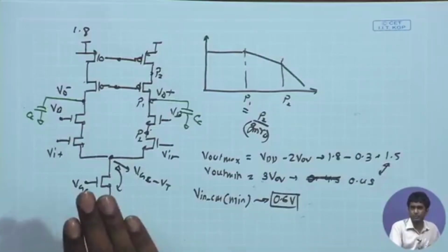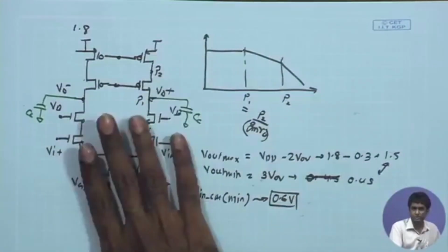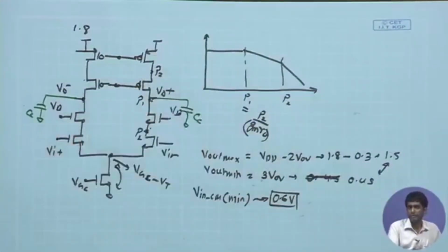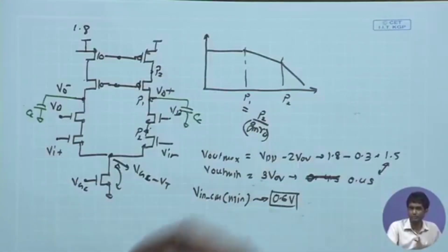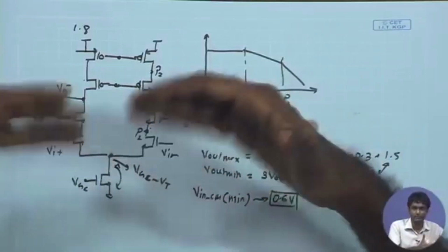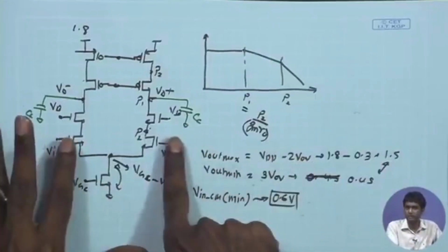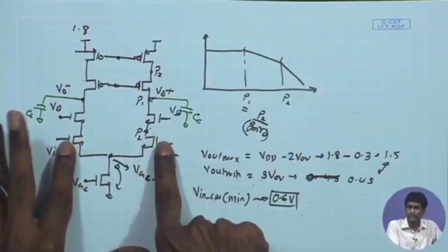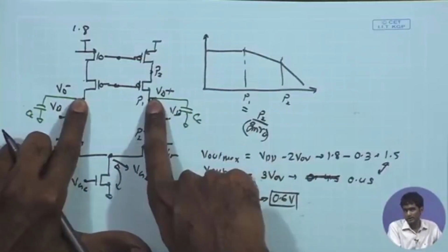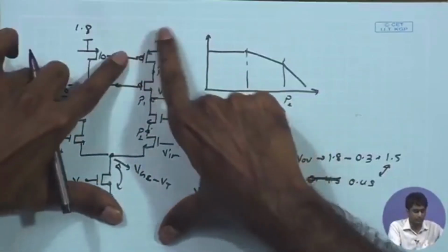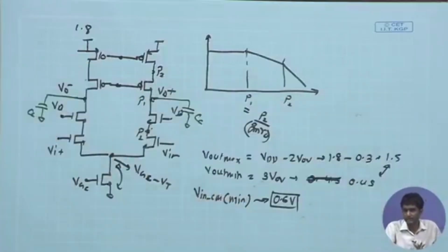So, any question before we try to look at an alternate scheme, which is a folded cascode scheme, which can resolve this issue of DC bias and the swing, at least the input swing. And then also we have to look at a biasing scheme through which we can get the best possible output swing. So, the next discussions look at the folded cascode topology, where the constraint on the input swing and the input DC biasing is resolved, and second, the output swing considerations, where I need to set up the appropriate bias point for these transistors so that my output swing is maximized.